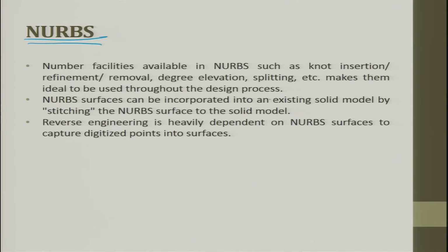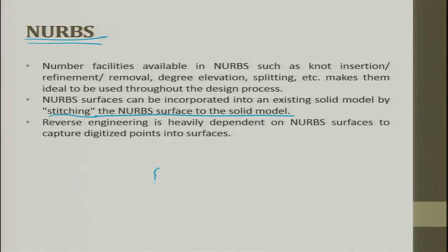NURBS surfaces can be incorporated in the existing SolidWorks by stitching the NURBS surface to a solid. So, if you want to add a patch to the solid surface, it is possible. Reverse engineering is heavily dependent on NURBS, wherein you have point cloud data.